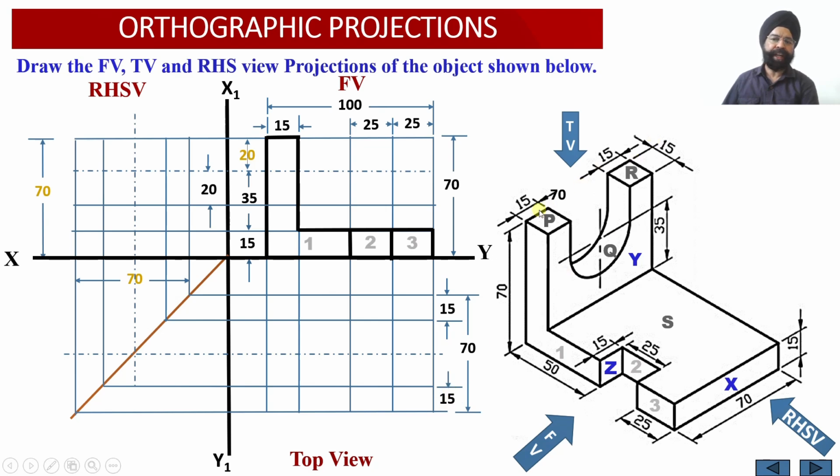Now these two webs, that is P and R surfaces, I am able to locate. So this is my surface R, you can check. This is my surface R, which is a square having a cross section of 15 millimeter, and this is my surface P, which is again a square having the edge equal to 15 millimeter, and this remainder is my top view, right? So this is the top view of this circular cross section. And what are the dimensions? Dimensions are the width equal to 15 millimeter and the depth equal to 40 millimeter. So I have obtained surfaces P, Q and R over here. Right now I have also got the location of the slot. So all the edges have been marked over here in the top view.